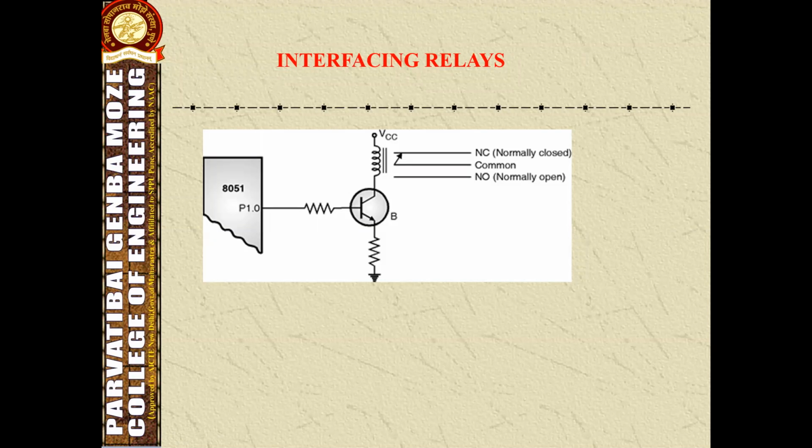A relay is an electrical switch that opens and closes under the control of another electrical circuit. In the original form, the switch is operated by an electromagnet to open or close one or many sets of contacts. The relay consists of a coil of wire surrounding a soft iron yoke, which provides a low reluctance path for magnetic flux, a movable iron armature and a set of contacts.